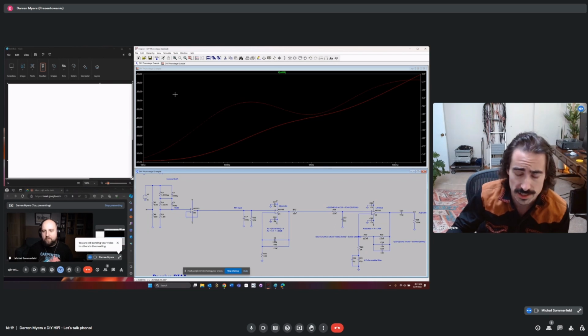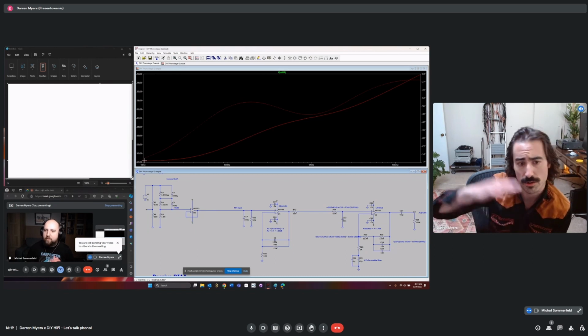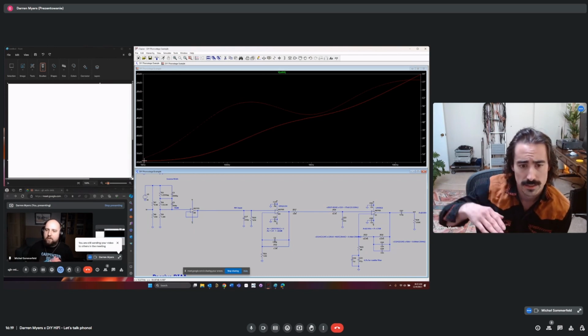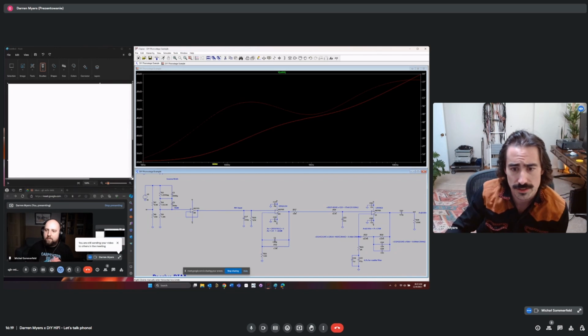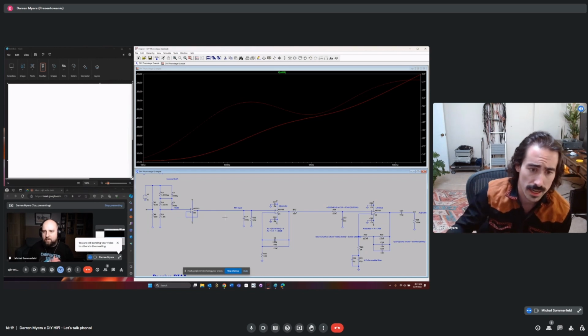The reason this was done is that if you were to have a flat signal, with no attenuation and no EQ cut on the record, the lower frequency energy would literally cause the tone arm to jump out of the groove. So they had to apply a correction so that at low frequency the amplitudes are really small, and at high frequency it's much higher.